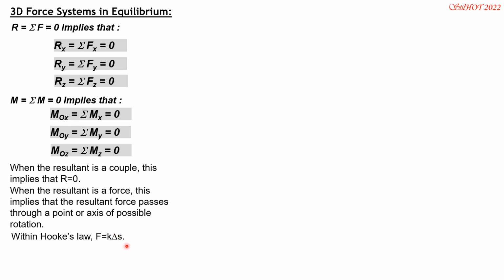And when you enforce moment about an axis, especially for supports with three unknowns, then you can reinforce this equation: moment about an axis equals position vector from moment center to line of action of force cross with the unit vector of that axis.